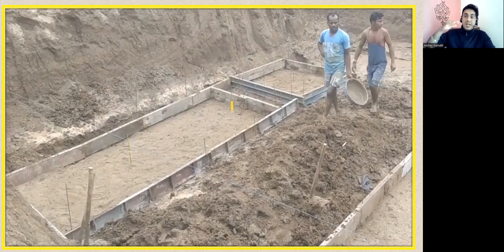And through that they'll come to a conclusion that they have to stop the concreting up to that level, isn't it? So what I'm trying to tell is, you can see a small thread here. They have marked this thread everywhere, and whenever the mason does the leveling, he'll come to a conclusion that this is 3 inch and this is where I have to do the finished surface.